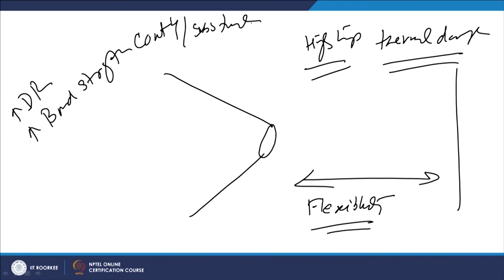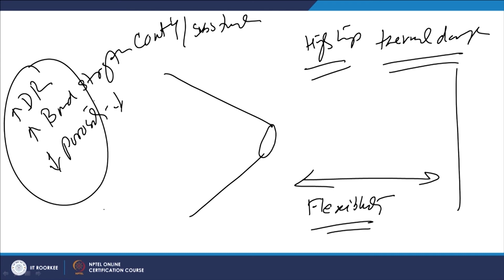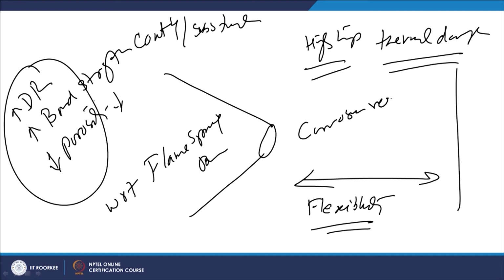At the same time, since it offers a moderately higher velocity, the porosity is also limited, because the impact of the molten metal at a moderately higher velocity leads to good firm contact between the splats, or between the molten metal and the substrate particles. So, the porosity is reduced, and all these factors are favorable as compared to the flame spray process, and this process is commonly used for depositing metals for corrosion resistance